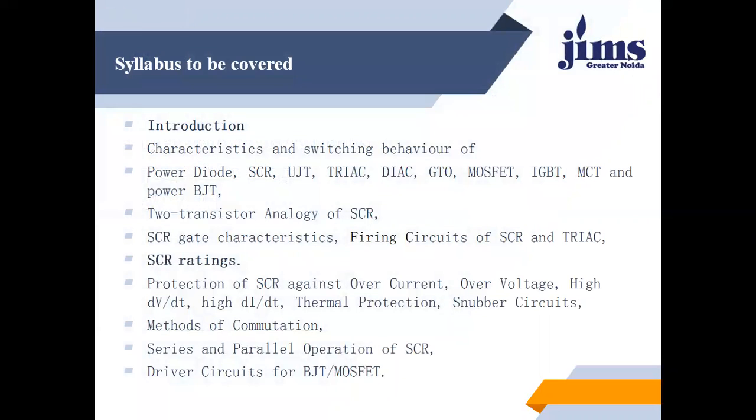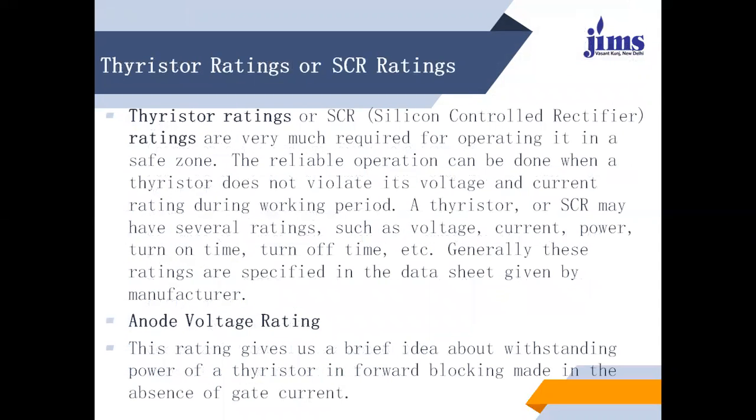So we will discuss in detail the various parameters which are important under this heading. Thyristor ratings or SCR ratings are very much required for operating it in a safe zone. Reliable operation can be achieved when a thyristor does not violate its voltage and current ratings during the working period. The thyristor or SCR may have several ratings such as voltage, current, power, turn-on time, turn-off time, etc. Generally, these ratings are specified in the data sheet given by the manufacturer.